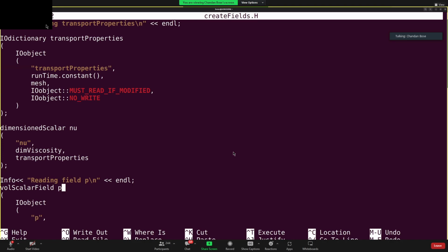That's because by default in OpenFOAM, all the simulations are 3D, all right? And we restrict the solution in the third direction by applying the empty boundary condition, all right? And that's why all the variables, scalar or vector, are defined as volume fields. That's important to know. Depending on your boundary condition, you can restrict it to a 2D simulation, but by default, it's a 3D simulation.